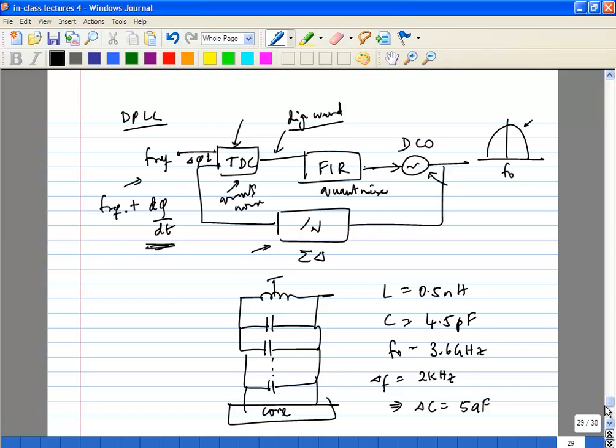That's a very good question. One of the problems with this kind of PLL is that you have a bunch of digital circuitry switching right at the control node. So you will definitely have problems with spurs at the output of the VCO. What you can do is try some kind of dithering, because now you have a lot of control over the digital word, to see if it helps with the spurs.